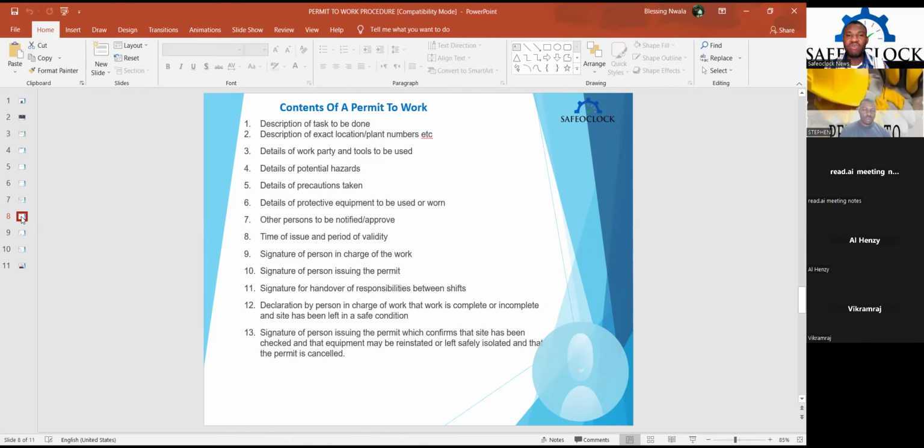Then our scope as health and safety permit coordinator is to confirm that the control measures stated in the permit to work document are available on site, and to confirm that the signature of the permit issuer is valid and accurate. Then we confirm that the date, the location, and the time of the permit are all accurate and complete. Then we countersign to give the go-ahead that the permit is now about to be used.